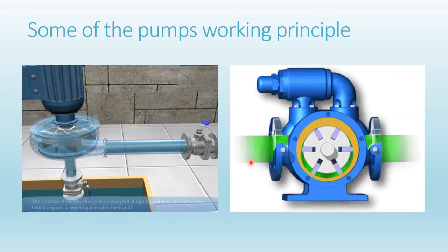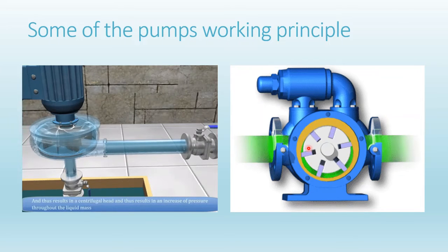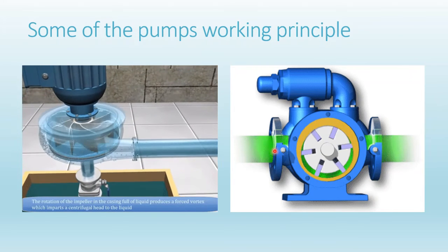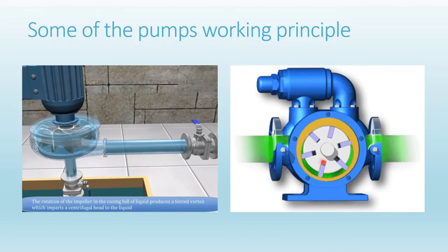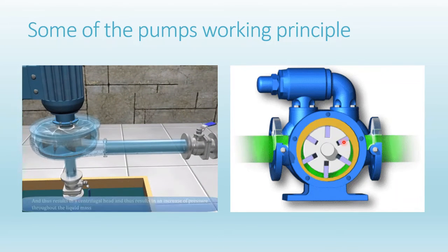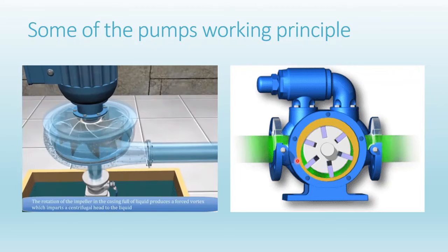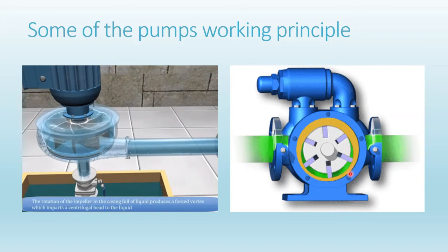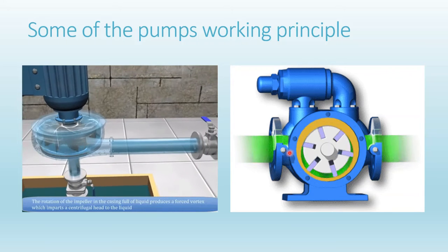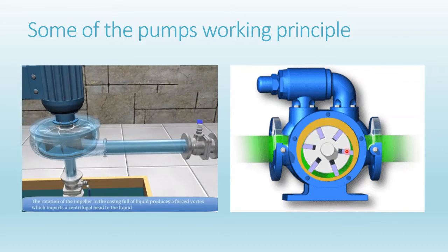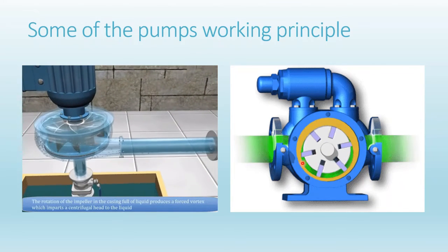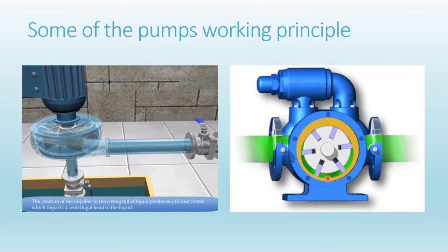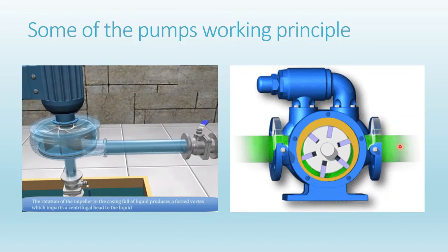That means when the vanes come out of the slotted part, the material enters the spaces between the two vanes and the pressure is built by the internal shape of the pump. The pump is not fully circular, it is eccentric, meaning the pump's internal design itself increases the pressure. As I already informed, this is generally used for pushing the material. It sucks the material in this side and pushes it out to this side.